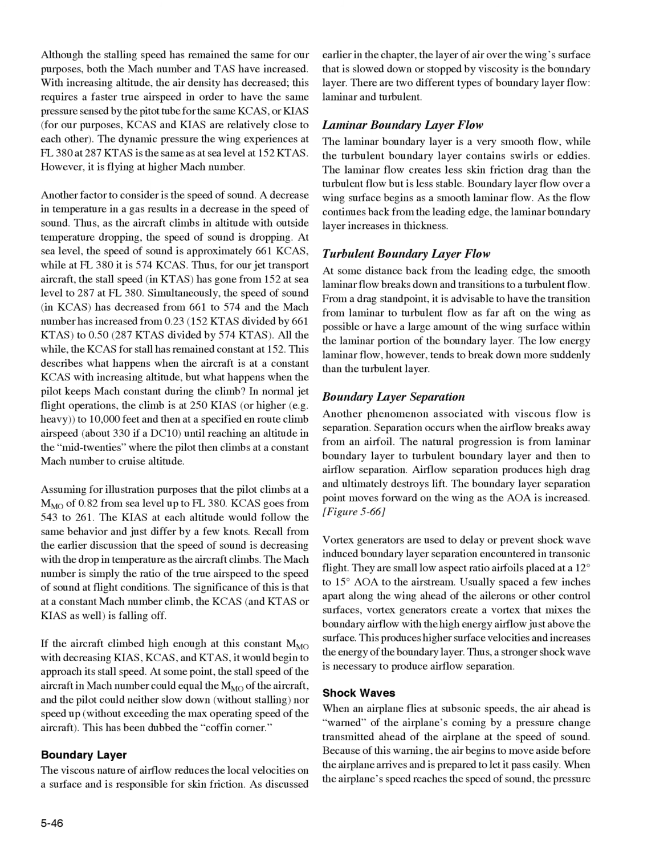Although the stalling speed has remained the same for our purposes, both the Mach number and TAS have increased. With increasing altitude, the air density has decreased. This requires a faster true airspeed in order to have the same pressure sensed by the pitot tube for the same KCAS, or KIAS. For our purposes, KCAS and KIAS are relatively close to each other. The dynamic pressure the wing experiences at FL 380 at 287 KTAS is the same as at sea level at 152 KTAS. However, it is flying at a higher Mach number.